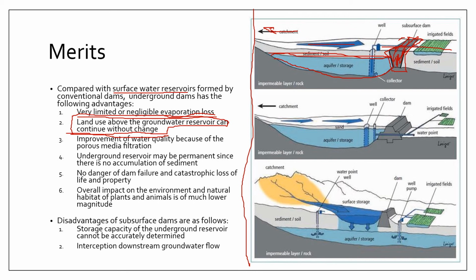Third point is that you have natural filtration in subsurface dams, so you have better water quality. And then fourth point is that you don't have the problem of sedimentation. All right? This is a major problem in dam reservoirs or in surface dams.